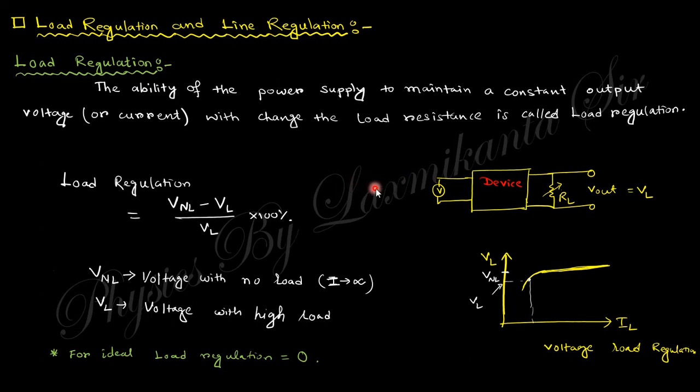There the input voltage is in but the output voltage is not connected to a device, that is called no load. So this is the voltage with no load. But when we connect the load, that is the mobile, then the voltage is known as the voltage with load, and this will be the VL. So their change with this VL is known as the load regulation.